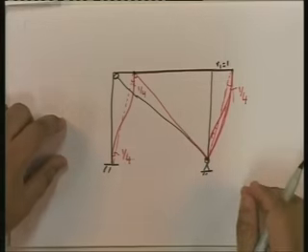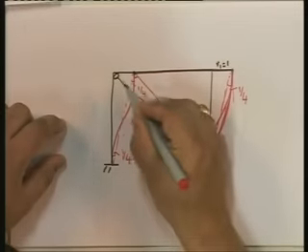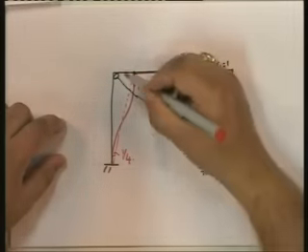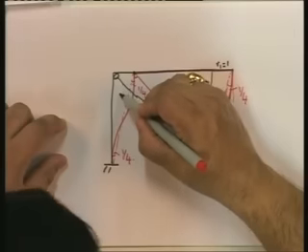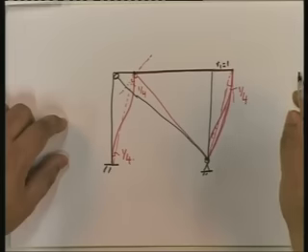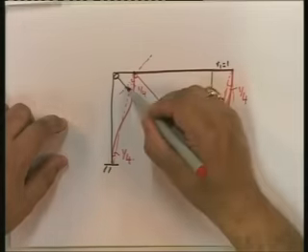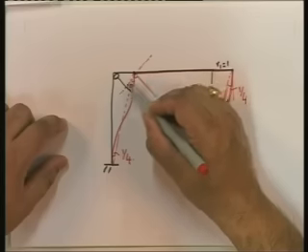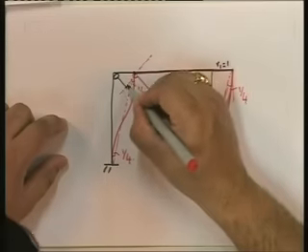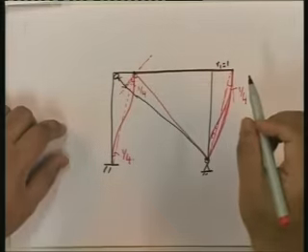Okay. Now, the other thing that we have to find out is how much has this member shortened by. So to find out how much it has shortened by, we need to draw the perpendicular. Because note that whatever it has moved perpendicular by, that does not change length. So when we drop a perpendicular here, this is the amount of change of length.